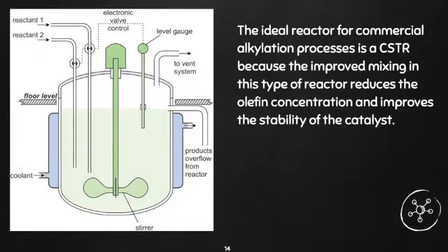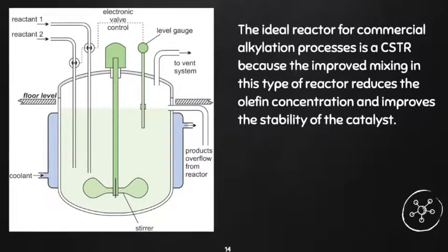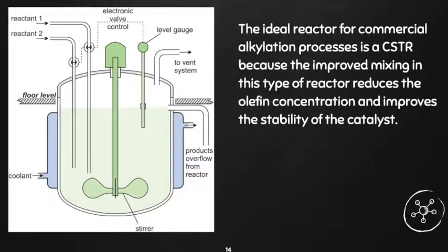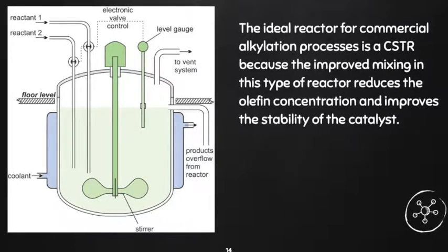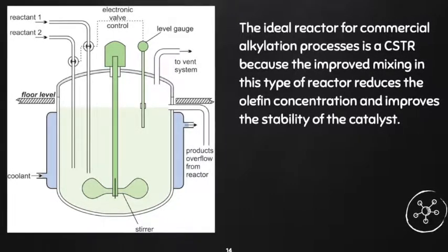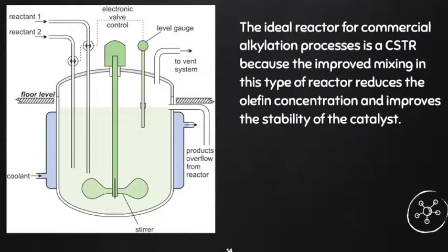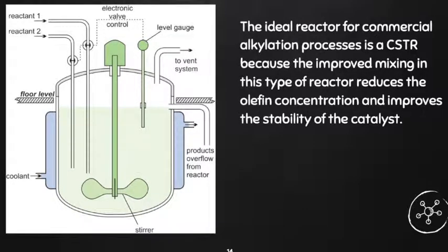Processes involving a PBR suffer from rapid catalyst deactivation once the oligomerization takes place on the first layer of the catalyst-packed bed, lowering conversion. In addition, the catalyst's lifetime is between 10 to 100 minutes, depending on the olefin space velocity and the paraffin-olefin ratio of the feed.